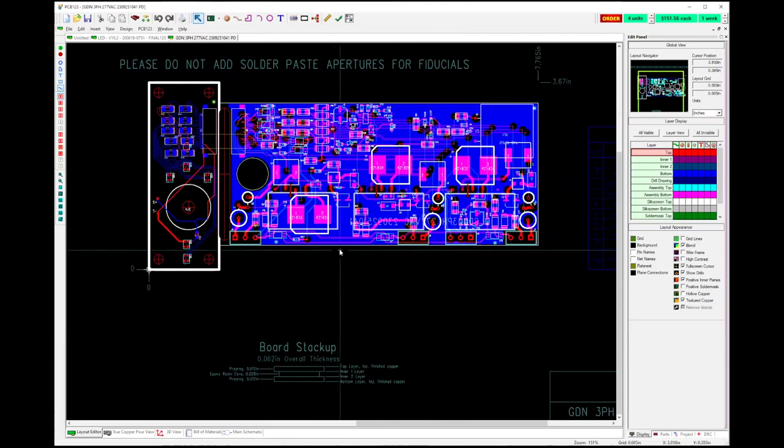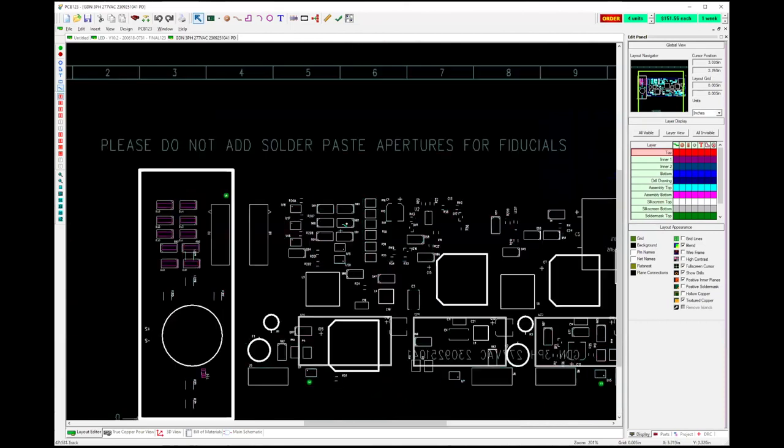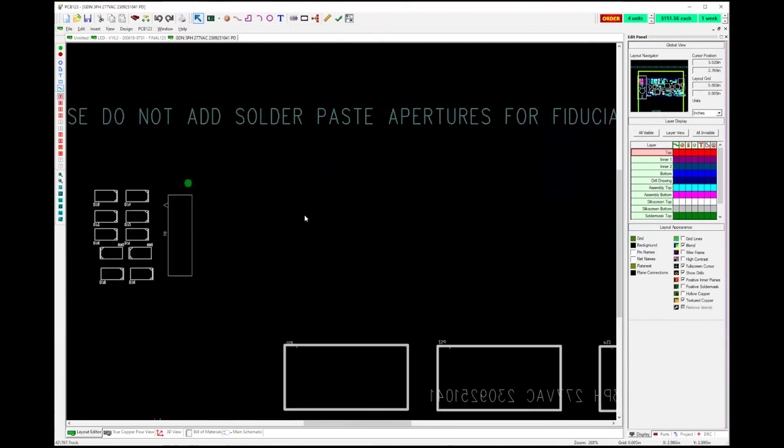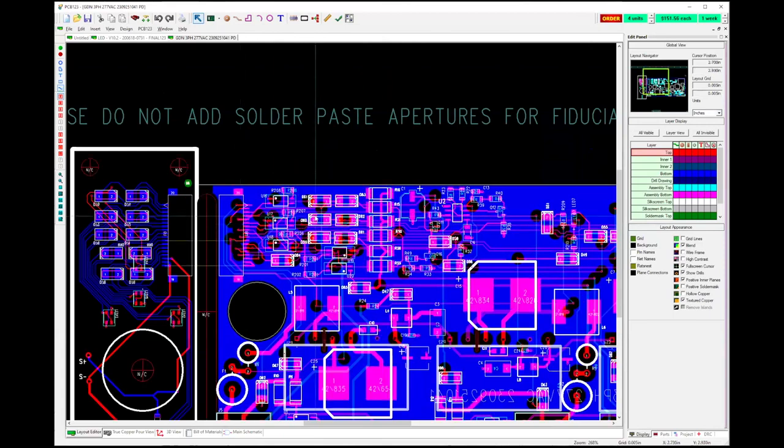The way I go about it when I route a board, I like to route the power and the ground and make sure everything there is hooked up. Then if I've got any clocks or critical high-speed wires, I hook up those to make sure that there's room to get them hooked up and logically laid out in a way that they're not going to be interfered with by other things. And then I go in and route any other non-critical nets, just basic interconnect stuff like this area here. There's really no high speed to it. They just had to hook up.